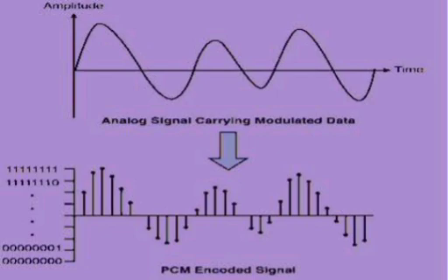Comparison of digital modulation schemes. Coherent ASK: S1 of t equals A cos omega c t, S2 of t equals 0. Its bandwidth is 2 RB. Its probability of error PE equals Q of root of A squared Tb by 4 N naught.